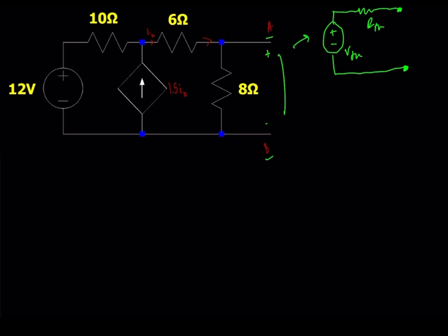Now to find that voltage, you can use any circuit analysis method you'd like here, namely the node voltage or mesh current method, which are two methods I've previously discussed. I'm going to elect the mesh current method just because this circuit lends itself well to that, with this current source in between two meshes. So the first step for that is just to label each distinct loop that is in the circuit here. We have two, and just assign them arbitrary current variables.